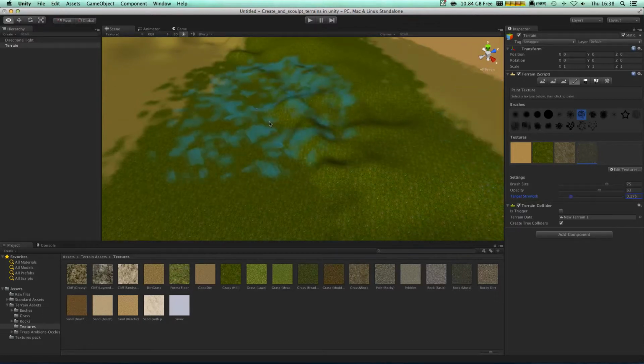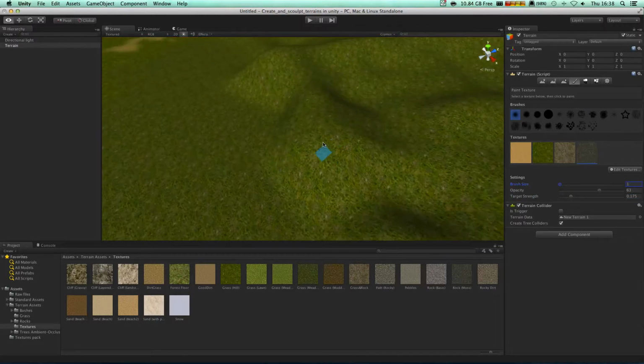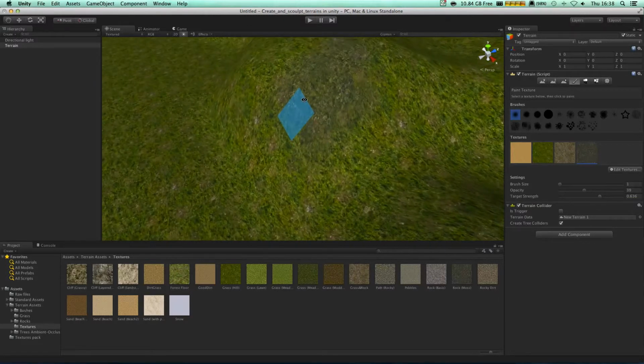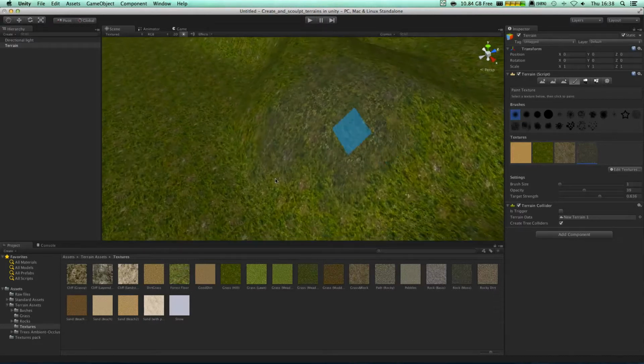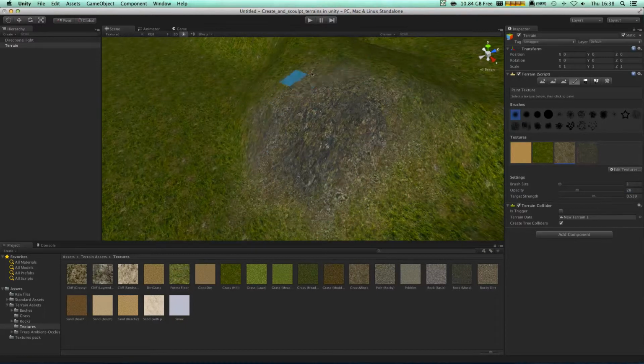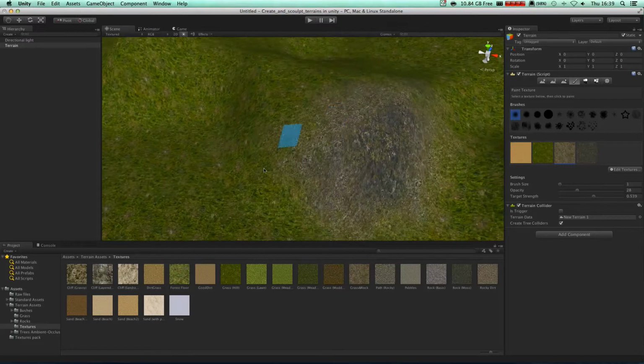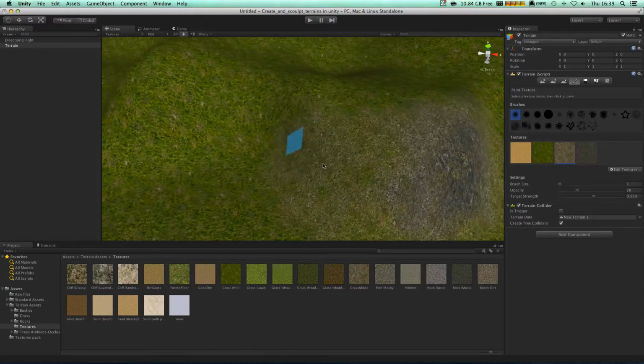So I'm gonna take this one with a pretty small target of 175. I can paint it. I'm painting this texture, but it's not that strong. As you can see, I'm painting this one now. I change my target strength and I'm painting it, but again not too much. And as soon as I change it, look what happened. And in this way, I can blend between the textures. For example, this one gonna be kind of a rocky part. This one a bit stronger.